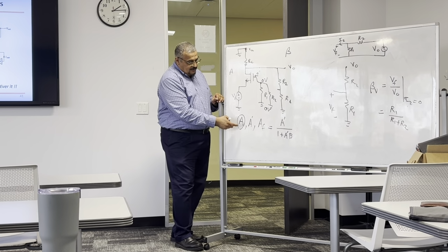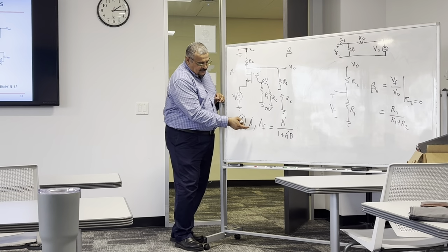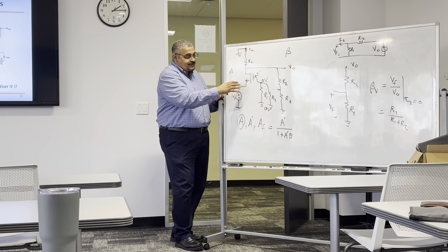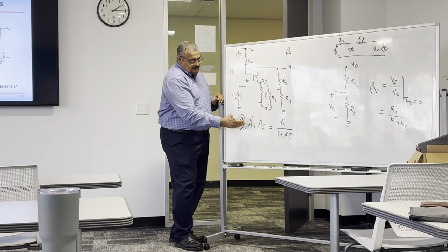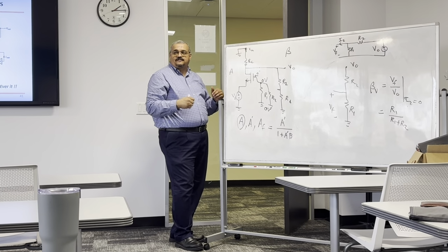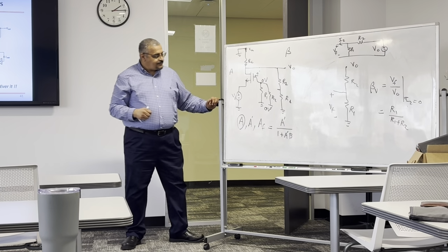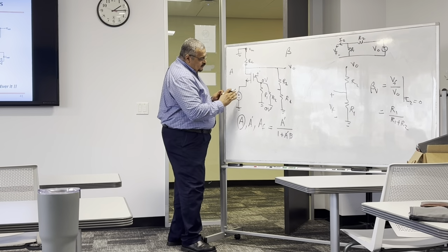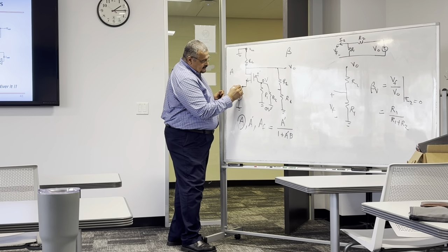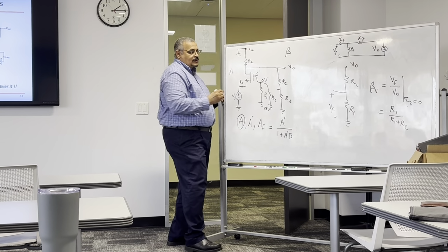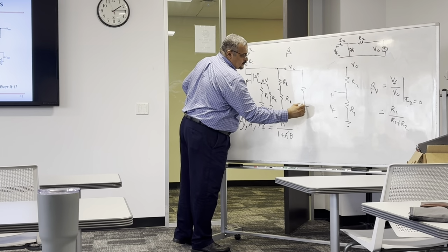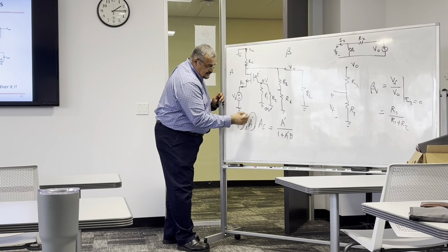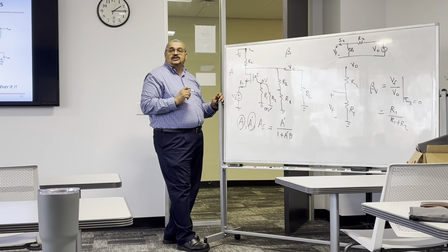Okay? We have an open loop gain without the feedback. And then a new one that's with the feedback effect but without the feedback connected. There's no feedback here. Then we have this with the feedback. Okay. One more thing. If you have RS here and you have an RL here, include them in calculating this one. Don't exclude them.